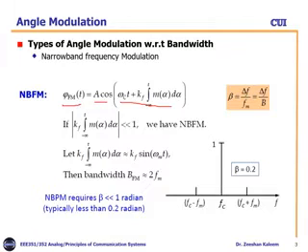So omega c t or 2 pi f c t, because we previously did calculation in 2 pi, so 2 pi f c t plus kf, and the integration of a message signal, 0 to t, m of alpha, or any variable which you like to assign here. So this is our FM equation.